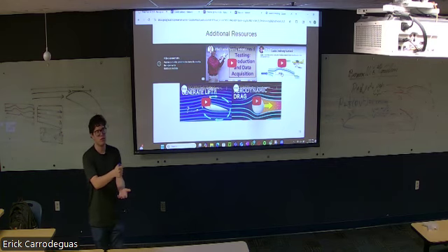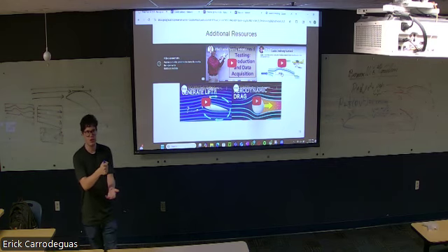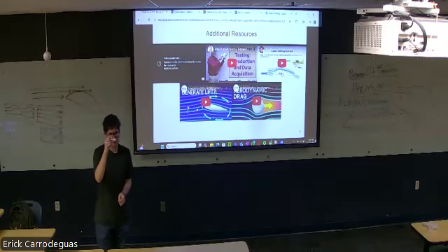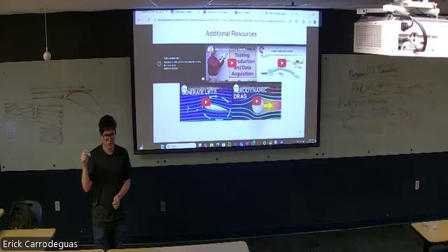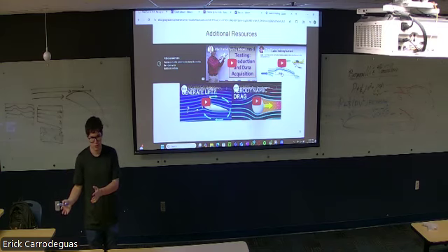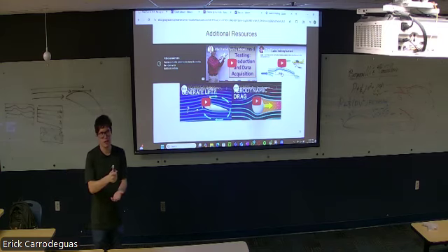So depending on how much is being deflected, we know the amount of thrust, and from there we can determine the drag. All of that's collected through an Arduino, and that Arduino just returns to us the values. The other option is just using a regular balance, and that will tell us the balance in pounds, because pounds is a unit of force, right? So that will tell us how much lift is being generated from that scale.